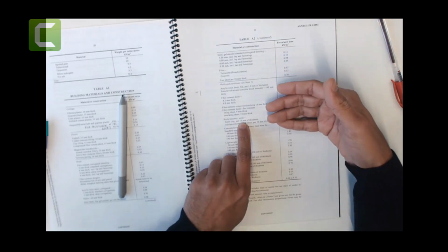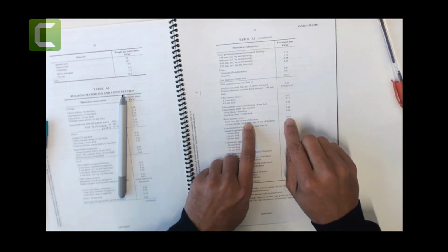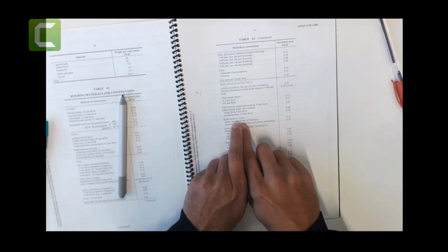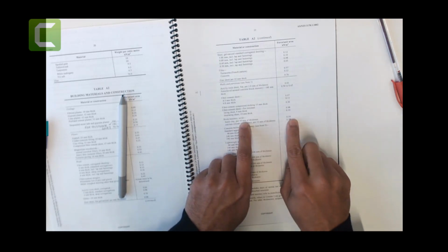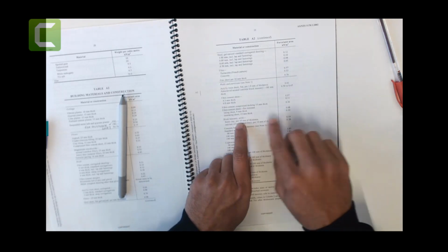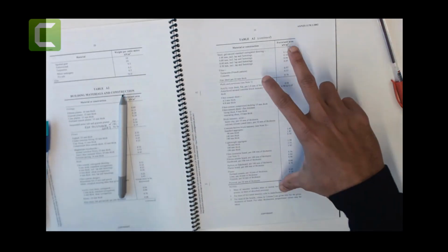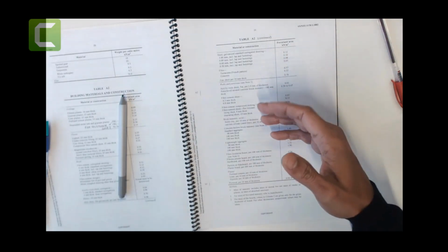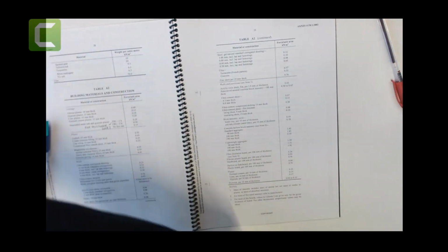So first of all, I convert this one for 110 millimeter thickness. That was the conversion that I made, because it's easy. If you know this one for 10 millimeters, then what would it be for 110 millimeters? Just math that you can use. Now, once you know how much pressure is applied from the 110 millimeters, you can just multiply by the height of the wall to convert into kilonewton per meter.